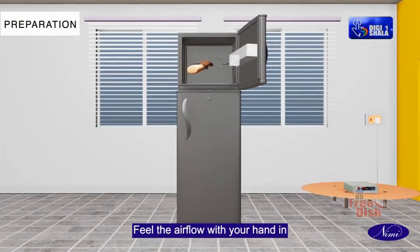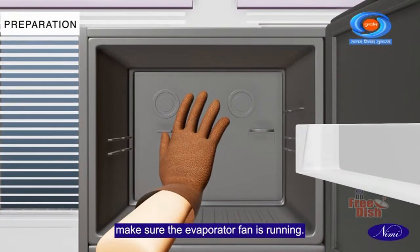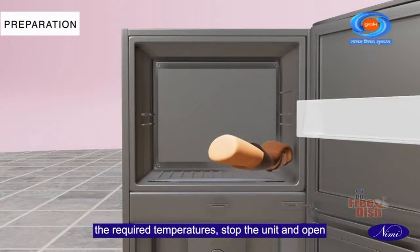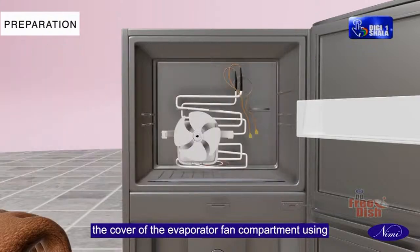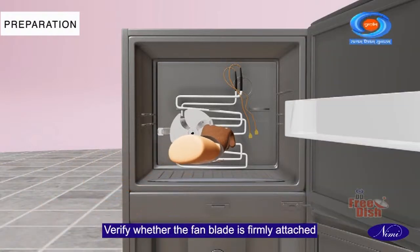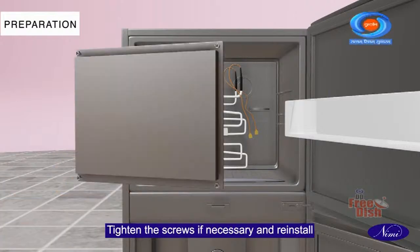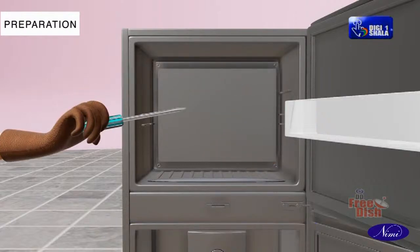Feel the airflow with your hand in the freezer and fresh food compartments to make sure the evaporator fan is running. If the refrigerator is running but not reaching the required temperatures, stop the unit and open the cover of the evaporator fan compartment using short screwdrivers. Verify whether the fan blade is firmly attached with the blade set screws. Tighten the screws if necessary and reinstall the cover of the evaporator fan compartment.